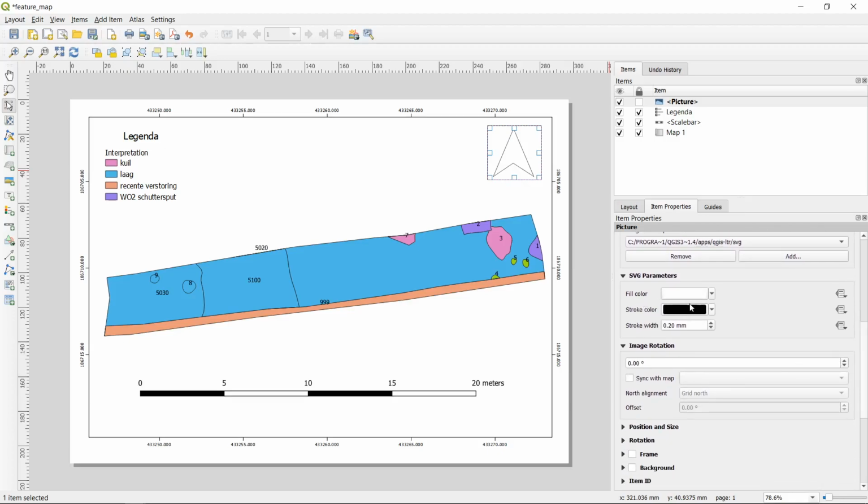Now, it goes without saying that you can then adjust a lot of properties of that north arrow. So the interesting thing, I mean, the function is called image, but we are actually not inserting a raster in this case, but a scalable vector graphic, which is SVG, so the word vector says it already. This is actually a polygon that is scalable, which we can change the fill color and so on. So let's do that, and we have a very nice black arrow, and you can see that we can change it without it losing any sharpness or whatever.